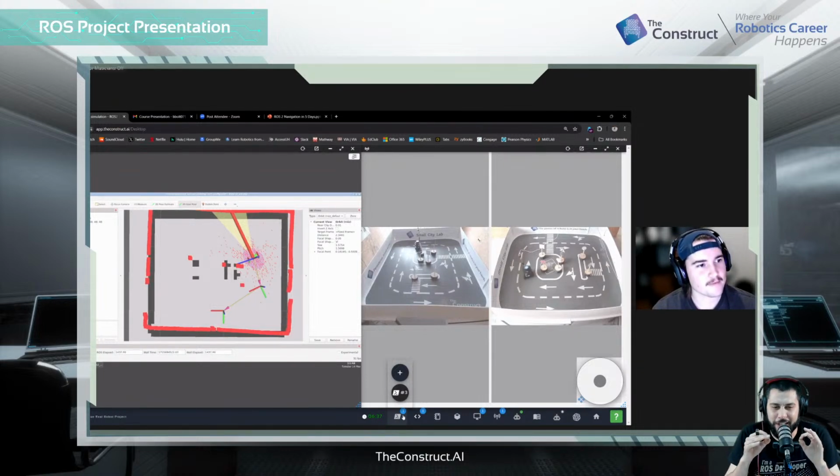Sometimes the static TFs get a little bit of trouble transmitting over the wire, because the static TFs, which means the base footprint to base link to the LiDAR frame, all the ones inside of the robot, those are static. And ROS2 only publishes those TF static messages once, because it doesn't make sense to just keep publishing the same info. So they just do it once.